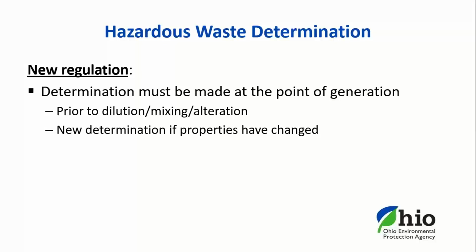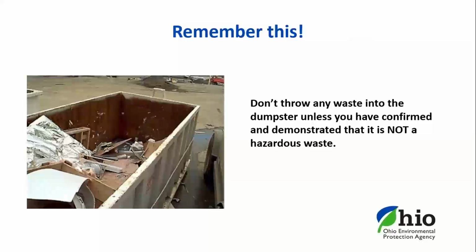The new rule specifies that a waste determination needs to be made at the point of generation, prior to any dilution or mixing or alteration. This is because that will change the properties of the waste, and anytime the properties change, a new determination needs to be made. And just another reminder to hold off on throwing waste into the dumpster until you've demonstrated that the waste is not hazardous.